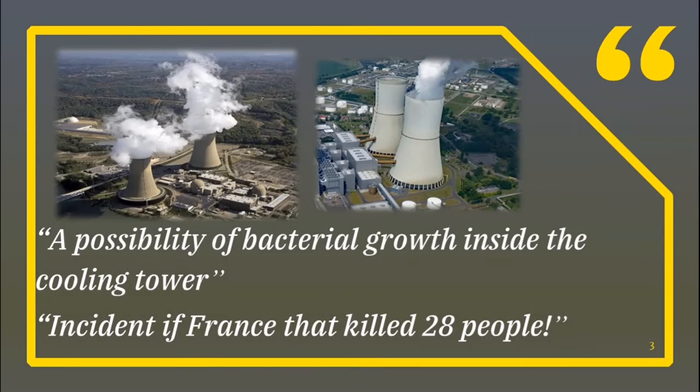Some people believe that the emission is toxic and can cause illness to the surrounding community. This is not true since the emission is just water vapor, but there is a possibility of bacterial growth inside the cooling tower. These bacteria can be carried up by the drift, which can cause illness to the surrounding area, just like the incident in France that killed 28 people. This rarely happens since the water quality is regularly checked and a dose of biocide is applied regularly.